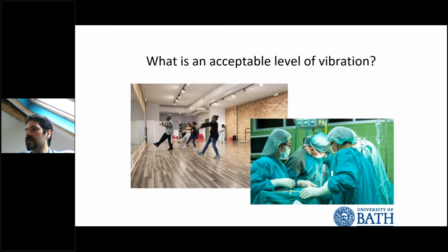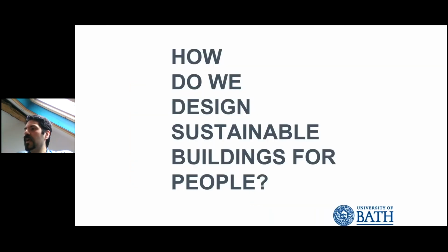So what is an acceptable level of vibrations? We don't really know the answer to this question yet, and probably there is no one answer. As much as guidance and standard writers would like there to be, it depends not only on frequency and amplitude of the vibration, but also on the duration, context, activities, characteristics of the people, and so on.